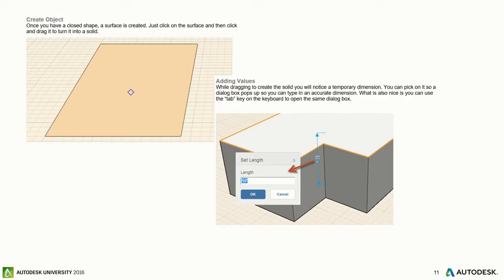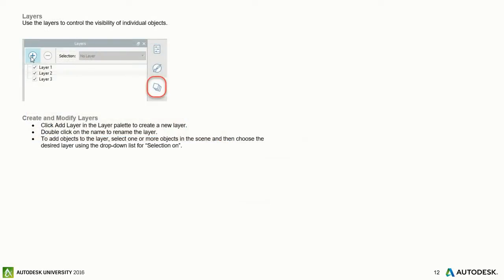So for you that work with Revit, it's called tab your life away in Revit. Some of my clients are like, Jared, is there a way to get rid of the tab my life away? Well, here's even more tab of your life away. So FormIt's into using tab also. In this case, if you want to do precision, I like to use the Tab key. It pops up a little dialog box. You can punch in the number. By the way, in FormIt 10 is 10 feet, just like Revit. Okay? If you want 10 inches, you got to get the inch mark in. Okay? So just a heads up with that.